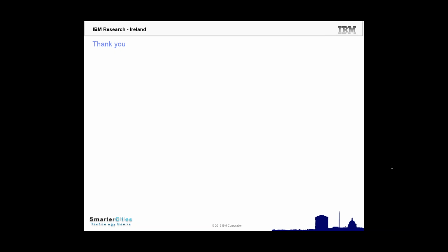Hello, this is Alex Stevanovic from Florida Atlantic University. Can I jump into this discussion? Maybe I can offer a slightly better explanation of how SCATS calculates the degree of saturation. Correct me if I'm wrong, but I think you are using the SCATS degree of saturation for this measure. It is not necessarily the full physical capacity, not really a full physical degree of saturation where everything to the maximal amount is accounted. It's more like a degree of saturation of 1 or 100% is set at some reasonable rate based on a formula which is beyond the scope of this conversation. They essentially measure the time and space that the detectors near the stop line are occupied by cars, and that value of 100% is not physically the maximum value.